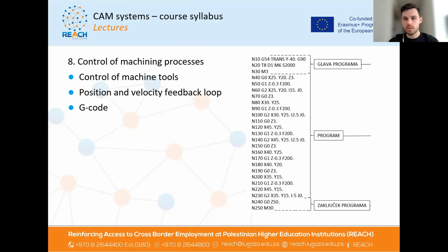And they will start with the really basic steps. So they will learn what the main codes are, what some additional codes are, and how the ANSI program is structured. To be more direct for you, every CNC program has its head, some first initial words for the setup in the program, has its own main program, and then the end of the program.